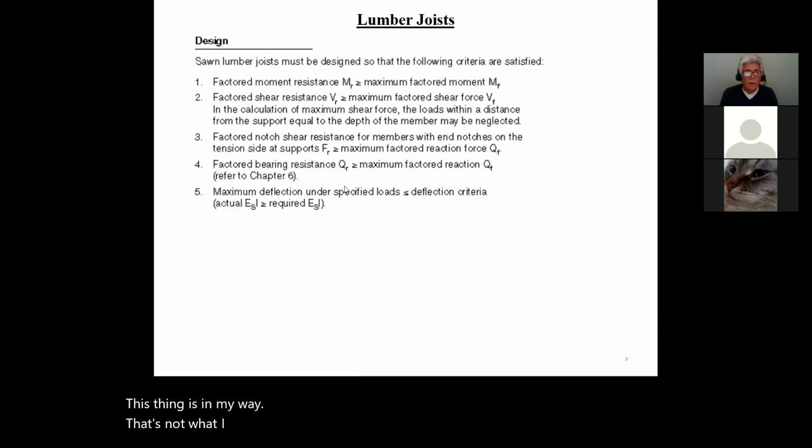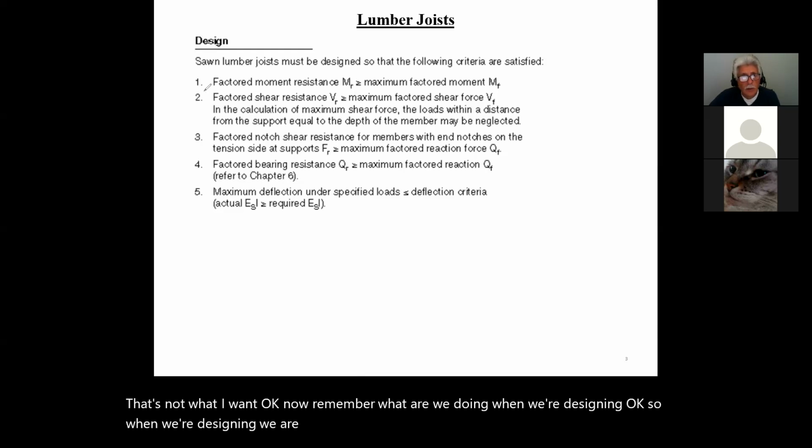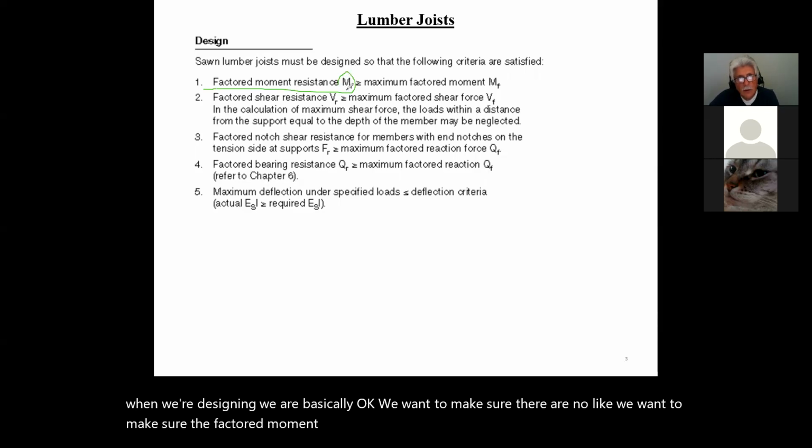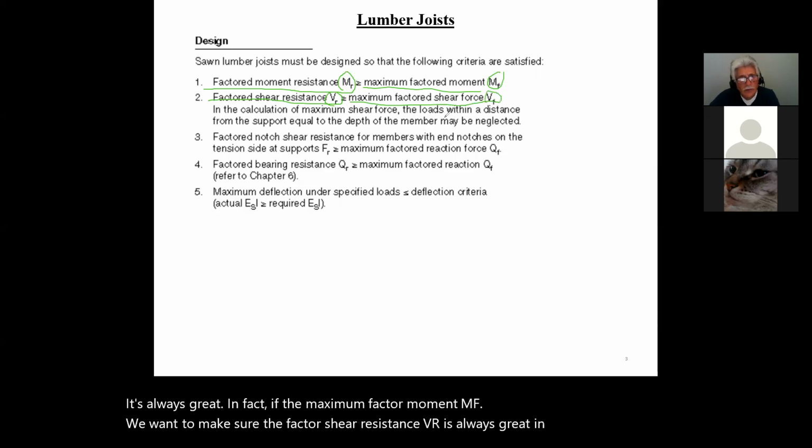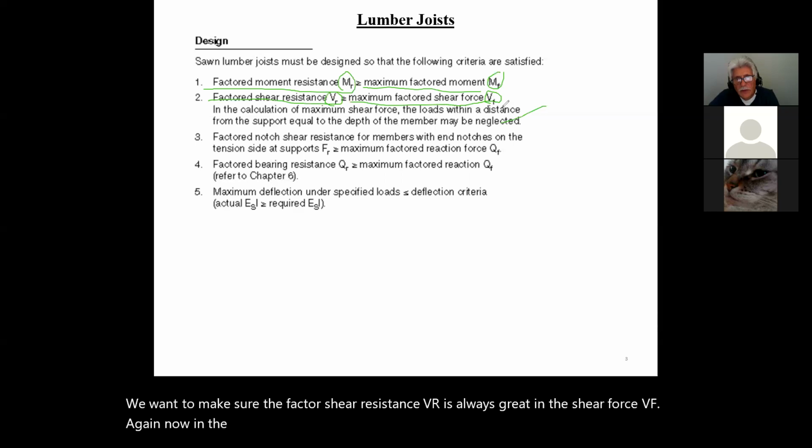Okay, now, remember, what are we doing when we're designing? When we're designing, we want to make sure the factored moment resistance MR is always greater than the maximum factored moment MF. We want to make sure the factored shear resistance VR is always greater than the shear force VF. Okay, now in the calculation, I don't even get into this. Okay, I don't care.